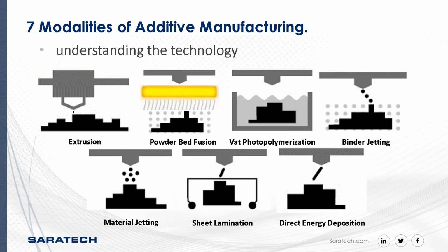And again, this is per layer. Once it fuses, you have a solid model, and so you have a 3D part. We'll move on to vat polymerization, known as SLA. It's a liquid polymer resin out of which the model is constructed layer by layer, and ultraviolet light is used to harden or cure the resin where required, also equaling a 3D model.